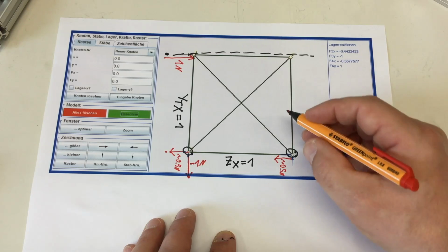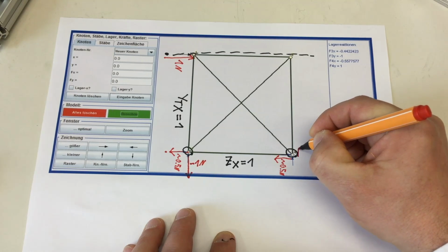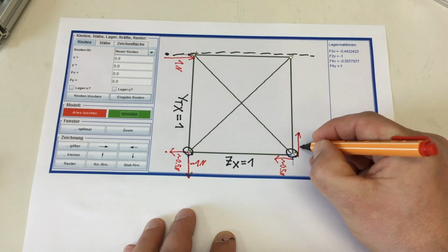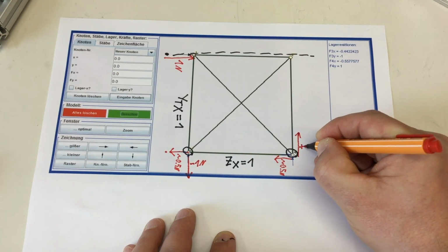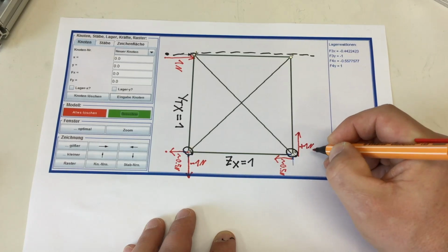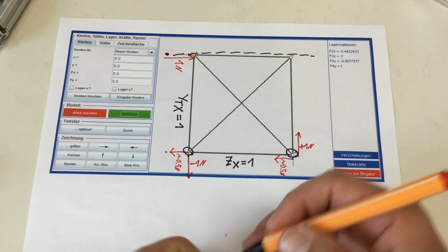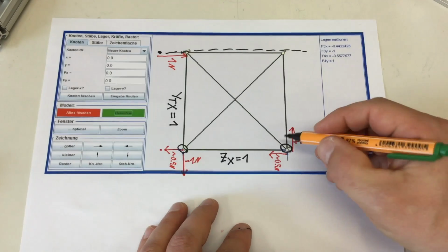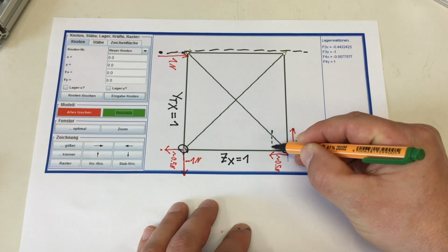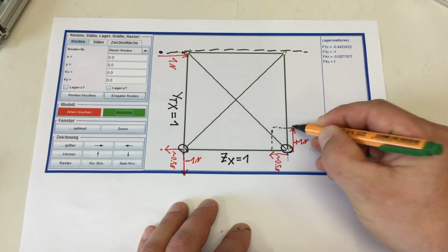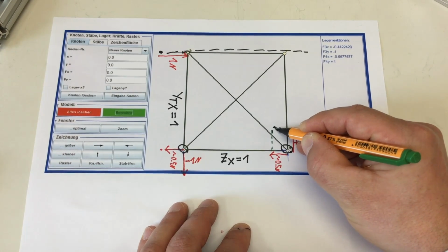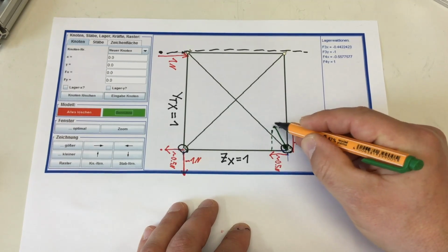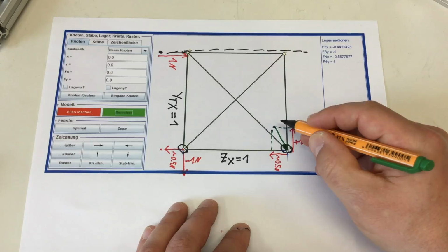And here it calculates something of +1 Newton. And now, if you remember the force triangle stuff, you can go in and basically construct and measure, if you do it with a ruler, the resulting force on the bearing.